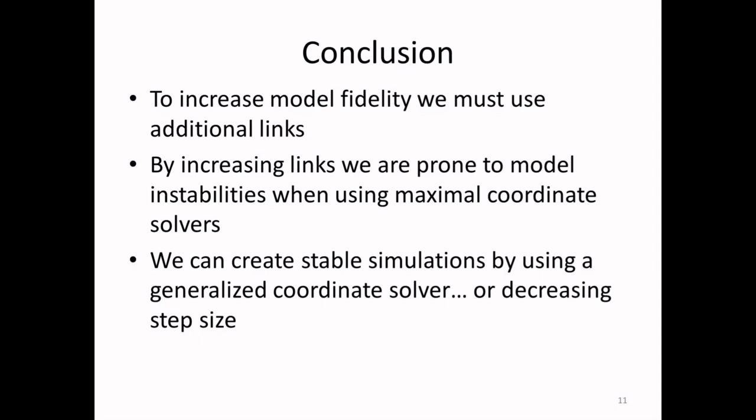or what we also found to be effective is to decrease the step size. The problem with decreasing the step size is that we're currently by default stepping at 0.001 seconds, which is 1,000 hertz.